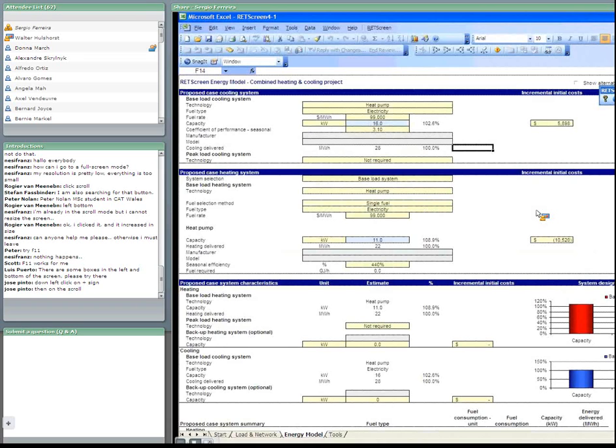So here we define that our electricity is generated using natural gas that has kilograms of CO2 per megawatt hour. We also include the transmission and distribution losses because this will have a slight impact. It will increase slightly the CO2 emission factor. As you can see, we go from 439 to 477 kilograms of CO2 per megawatt hour.